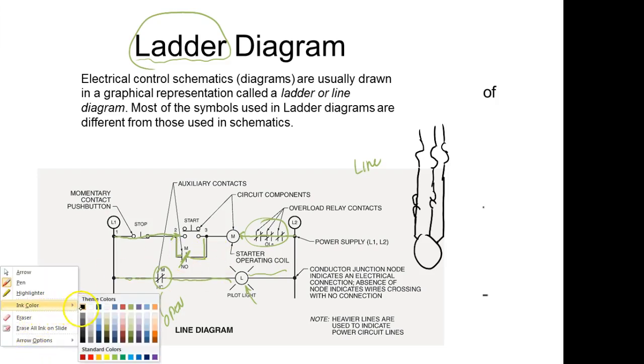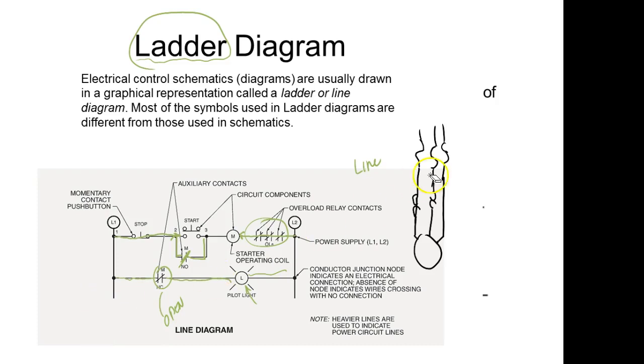So what happens is that if the motor stalls, these overload sensors will sense over current, but over time. Y'all understand what it means? So they will let the start current come through and allow the motor to start. But if the motor don't start, or if it stalls, then these guys are going to sense that. And what it does, it opens one of these contacts right here. So this would be three-phase. If it opens one of these contacts, then what's going to happen to the relay? It's going to drop out, right? Or it's going to de-energize.